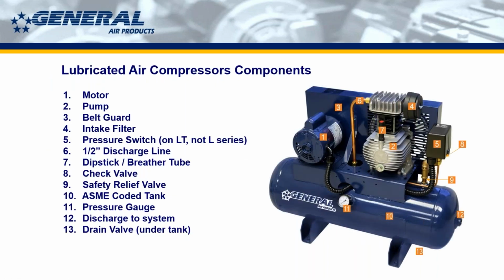Some of the major parts here that I like to call out. So we've got the motor, we've got the pump, intake filter, number 4. We do not sell a lot of intake filters, which means in the world, there are a lot of clogged intake filters or filters with holes in them that are bringing debris into the pump, and that stuff can really break the pump. So intake filters are really important, and I like to call that out there on this lubricated unit. That's where it is. I'll show you where it is on the oilless ones as well.